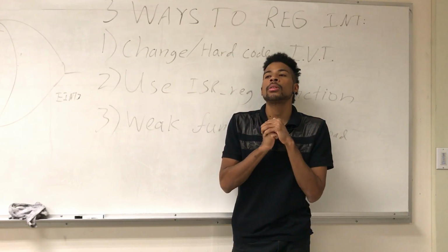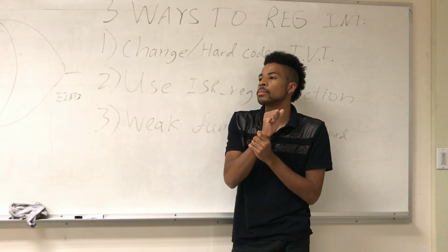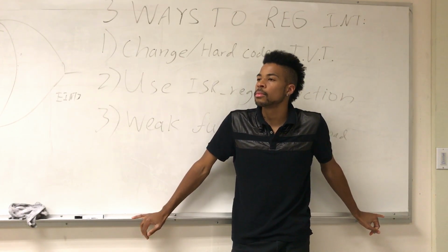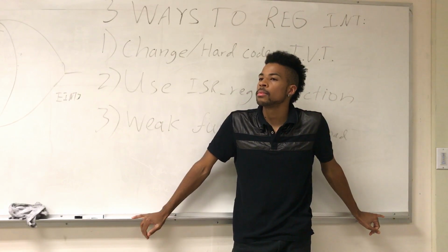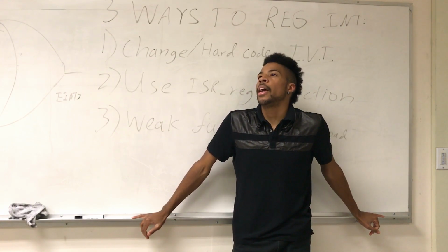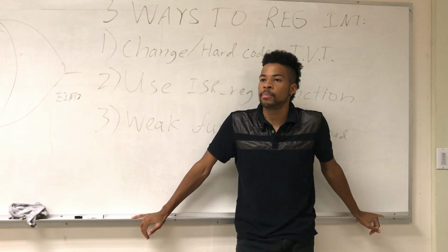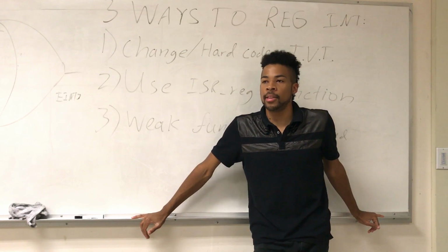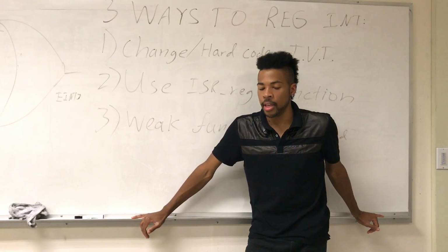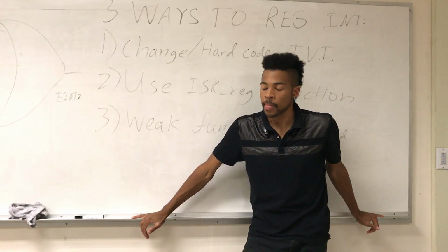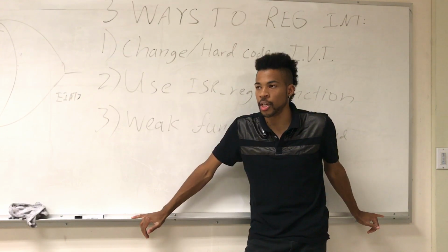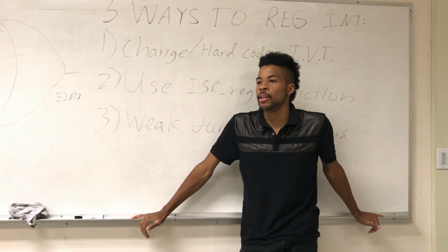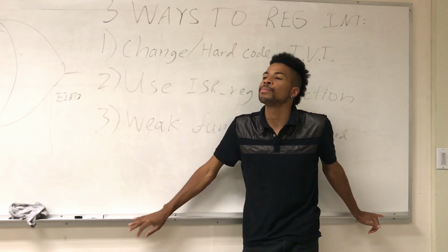Any other questions? You mentioned callback before. I was writing stuff and missed it. Were you referring to the interrupt service routine? Yes. So you're going to assign a callback or an interrupt service routine per pin. You specify the port, the pin, the rising, falling, or both, and then you specify an interrupt service routine for that particular pin. But effectively, it's going to be like a software callback. You'll check it and say, okay, this is the situation, call this function.